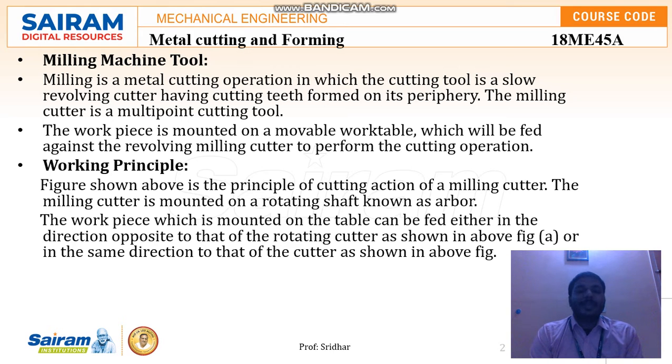Similarly, it is difficult to produce slots or keyways for very small components. That is one of the major uses of the milling machine, for keyways, slot milling, slot cutting, and gear cutting. In gear cutting, different types of teeth can be formed. For that, we first fix the workpiece with the indexing table, then we fix the cutter.